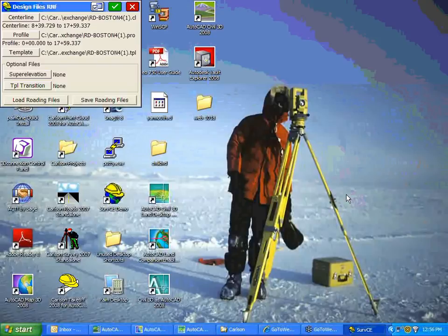Good question. Do you need to use new drawings every time you import Land XML? You do not have to use new drawings. You can continue to use the same drawing. Now, let's say you're XMLing in some point data, and your coordinate file has point data in it. Well, that's where point protection comes into play, or you could write to a new coordinate file, but you certainly do not have to open a new drawing every time.